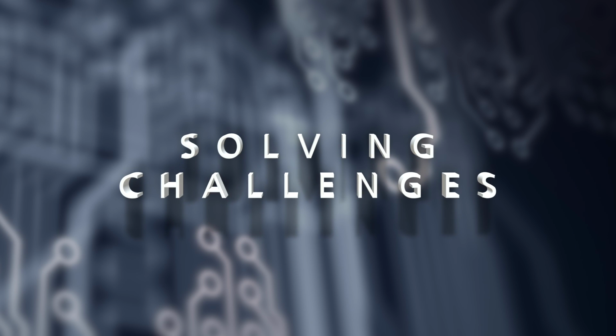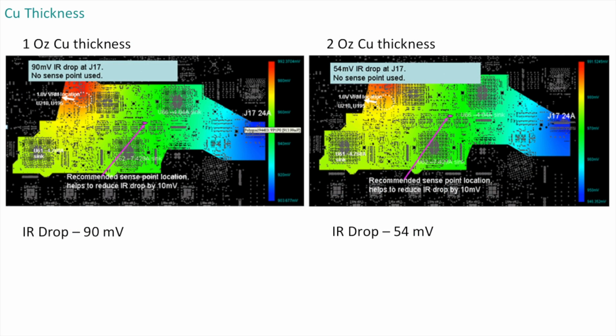So we ran the first cut of simulation and observed the results, and based on the results we modified the copper thickness from half ounce to 1 ounce and added additional plane layers. Then we ran multiple iterations of the simulations, and we observed that the results improved.